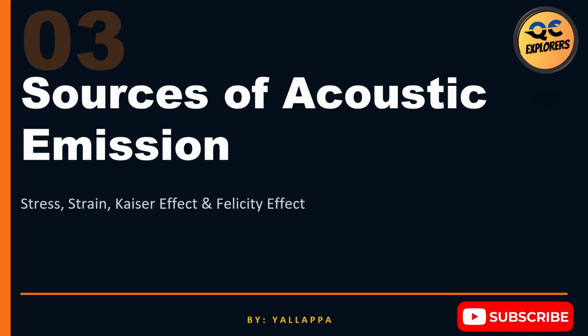Acoustic emission is generated whenever energy is suddenly released inside a material. Now, in industry, the most important sources are crack growth and plastic deformation. Those are the primary sources inspectors are usually concerned about. But AE can also come from secondary sources like corrosion activity and phase transformation. Now remember this important point. The released energy travels through the material as elastic stress waves, and those waves move outward like a spherical wavefront until they are detected by piezoelectric sensors mounted on the surface. This is why sensor placement becomes extremely important in AE testing.